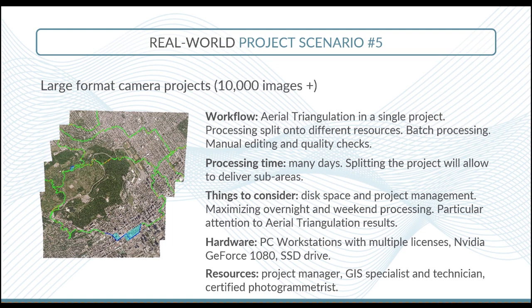And now you have to go back to the aerial triangulation and restart all the processing. You can lose a lot of time if you are not careful with the aerial triangulation results. For this reason, I would probably give the aerial triangulation report to a certified photogrammetrist, so they could look at it and be sure that it's meeting all the specifications.